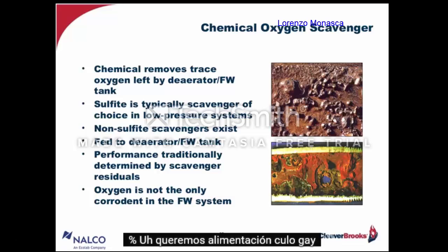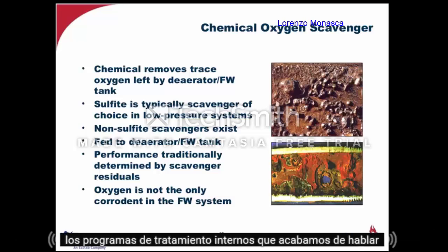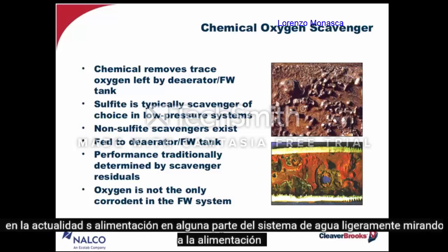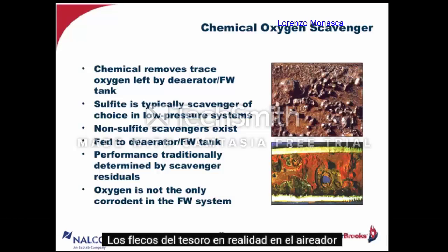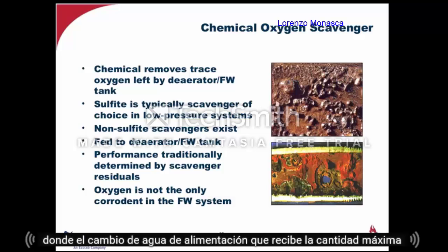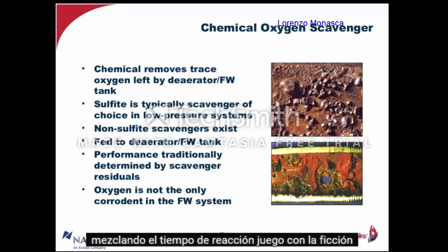We look at feeding the internal treatment programs that we just talked about into that feed water system someplace. But we look at feeding the oxygen scavenger actually into the deaerator or the feed water tank so that it gets the maximum amount of mixing and reaction time with oxygen.